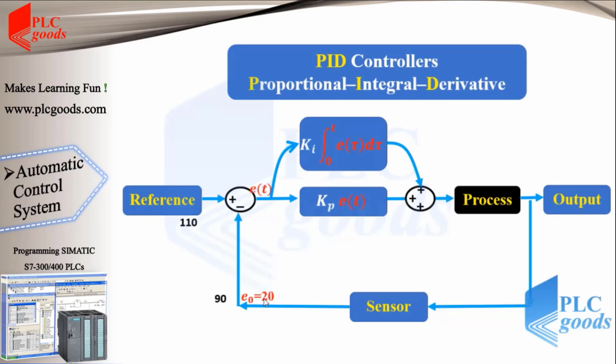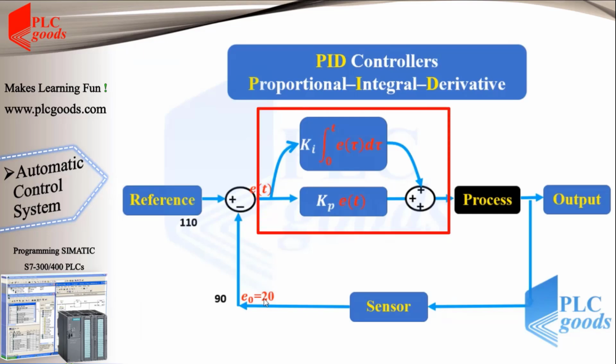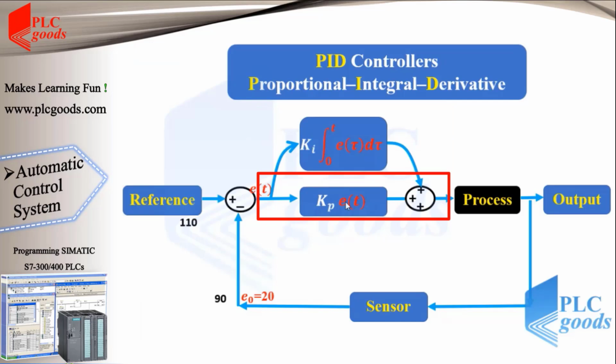As you can see, the output of my PI controller consists of only two sections. In the beginning, because elapsed time is small, the output of the integral section is close to zero and the output of the proportional section is not zero. So the proportional section plays the main role to determine the output of the controller. A non-zero number causes the controller to open the inlet valve.